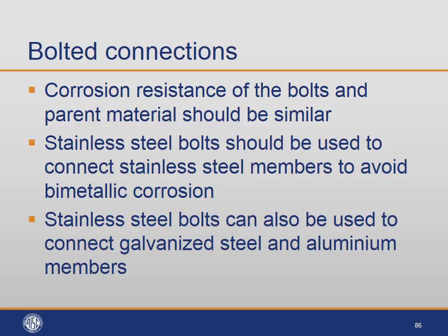Now, we covered last week the fact that you should use stainless bolts to connect stainless members. You don't want to use carbon steel bolts in stainless members. And also you can use stainless bolts in other metals to connect galvanized steel and aluminium members, for example.